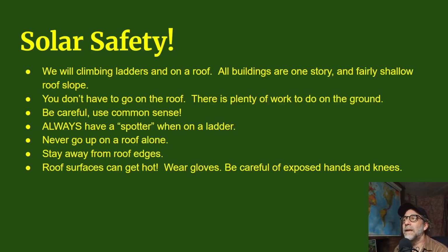Anytime you're going to be on a ladder, there should always be somebody at the bottom holding the ladder for you. That's very important. Don't ever go on a ladder by yourself. And never go up on the roof by yourself. There should always be a group of people up there together. When you're on the roof, obviously you want to stay away from the roof edges. Also, the roof can get hot, so make sure you wear gloves and be careful of your knees and your hands when you're up there.